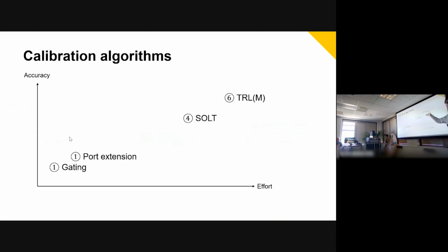So these are some classical calibration methods. Encircled, you see the number of standards measurements that you need, and each standard means space on a PCB, it means effort to lay it out, cost for the components. We got acquainted with a relatively young exception. It's called automatic fixture removal, which also needs just one standard, one reflection or one through, but still has quite good accuracy. It needs, I must admit, some fingerspitzengefühl, but once you have it, it's a real time and space saver.